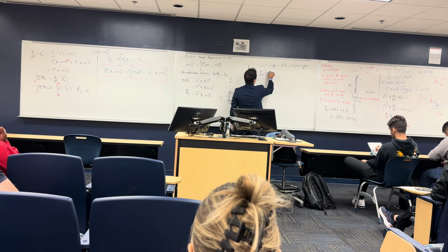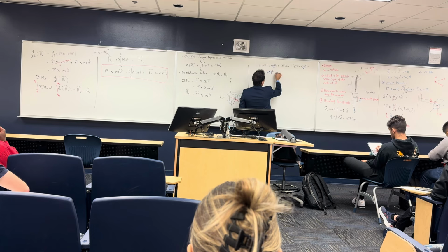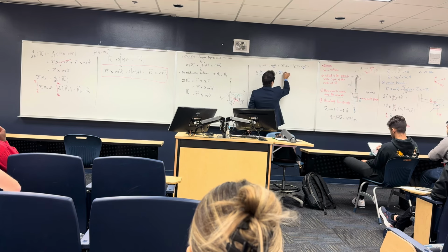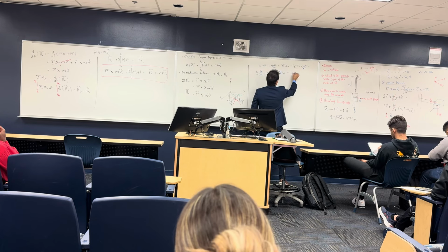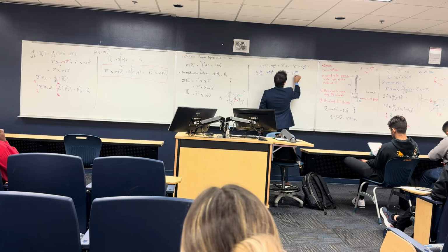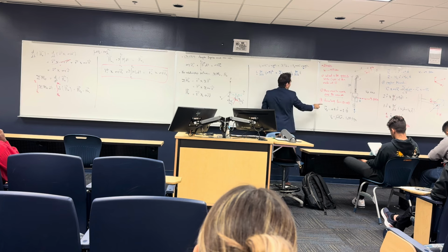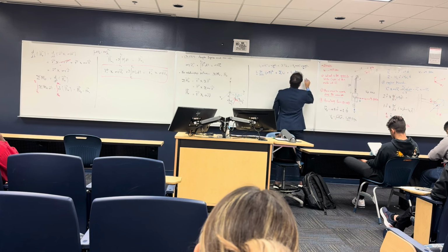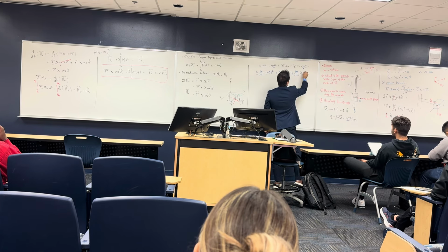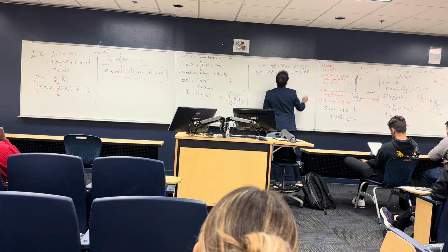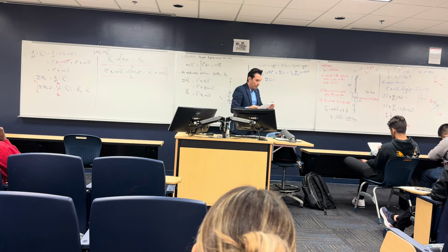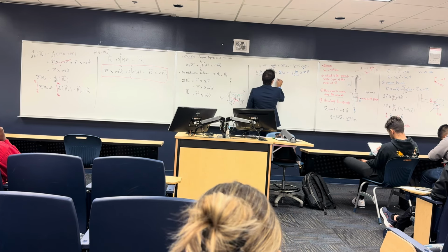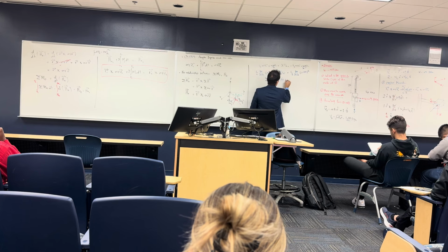So I have 0.5 squared, plus the work that we are looking for, coming from the R, is going to be equal to half 80 over 32.2 multiplied by V2, which we just got, the scalar quantity 0.077 squared, and we can get the work. So this is going to be equal to 1.13 feet pound.